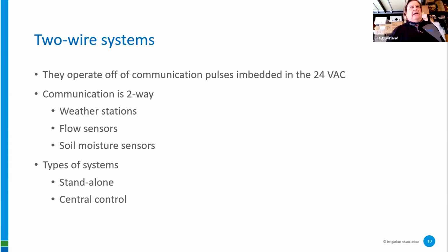In days gone by, I would have a broken zone 14. I would have a geyser going. I wouldn't know any better until somebody saw it and called somebody and says, hey, Frank, we have a beautiful fountain in the middle of the turf grass. Now, fountains should be someplace to go and enjoy, but they're not supposed to be in the middle of the turf grass, especially when it's supposed to be irrigating. Somebody's got to go check it out. That's the old way. Well, nowadays with technology, we can get an alert that there's a fountain going on. We need to go address it. And that's one of the benefits of having a 2-wire system with a flow sensing type decoder out there.